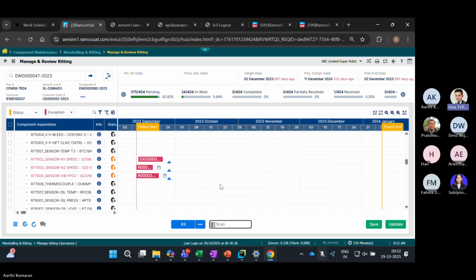So engines, APUs, and landing gears, we usually consider them as a complex assembly, and based on that, we follow the complex assembly maintenance process, which is what we do. Landing gear is 50-50. Some are treated as components, some as complex assemblies, but engine and APU are always treated as a complex assembly, and these are the streams in the framework that is used for complex assembly maintenance.